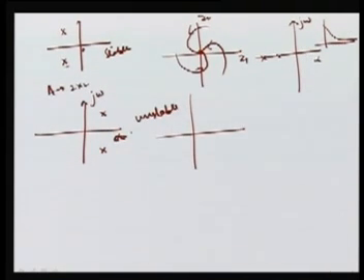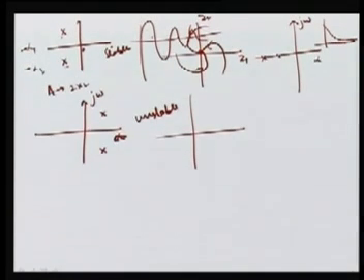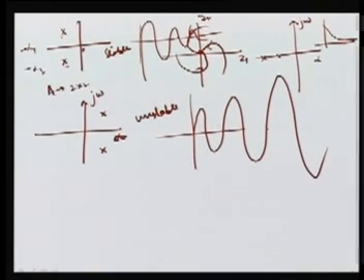But here, it will be oscillating, and the oscillation will keep on dying down, because here it is negative, and that is damping. So here we have minus alpha 1 and minus alpha 2 as well. So there will be oscillation, but it will be decaying. In this other case there will be oscillation and it will keep on increasing, and the system is unstable.